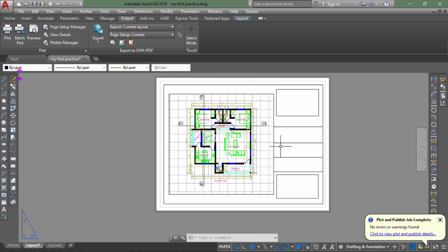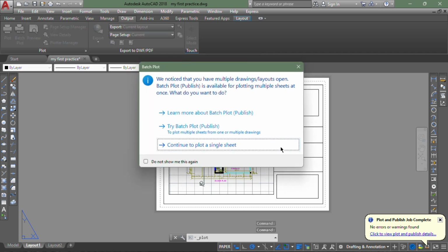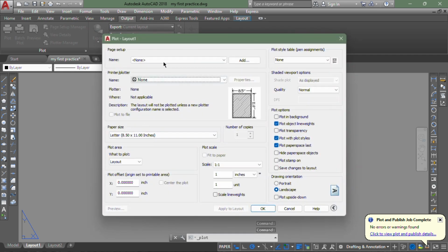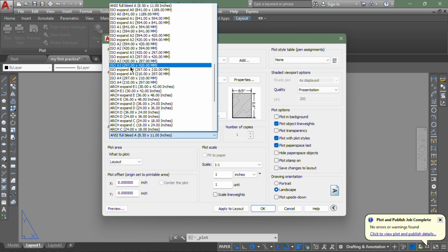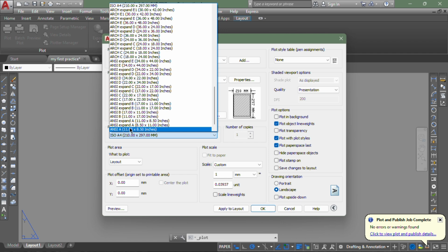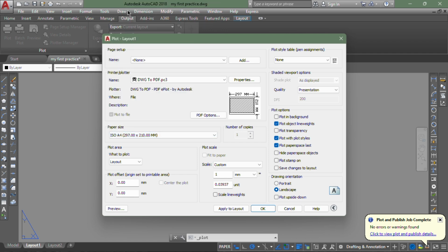So now we can just go ahead and plot, Control P, plot. Okay, let's bring back. Since it's not there, let's give it our plotting. The one we did earlier was for inside the main work model. That's why we are able to bring it back. Since now we are dealing with another thing, let's redo it again, presentation, and then let's pick our paper size. We are dealing with landscape paper size, and I think we cannot fit to paper here, right?